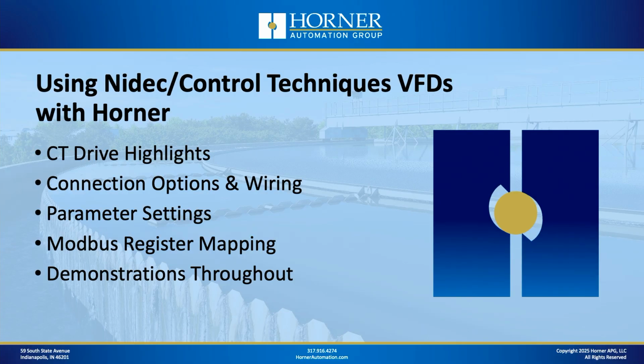Today we're going to start with some highlights from CT drives. We'll talk connection options and wiring with Modbus specifically. We'll talk different drive parameter settings. We'll go through Modbus register mapping, and there'll be plenty of demonstrations throughout.